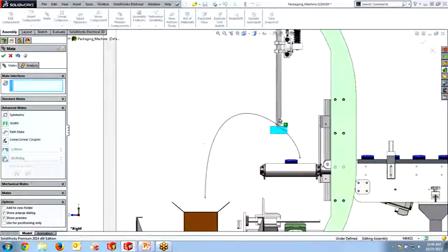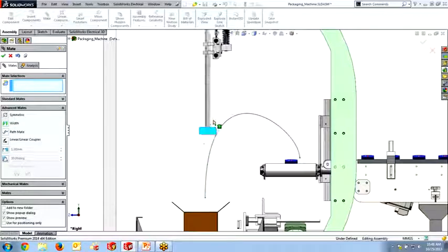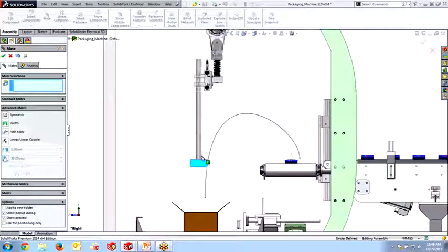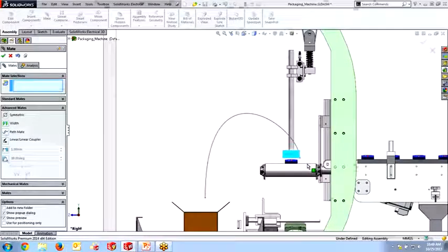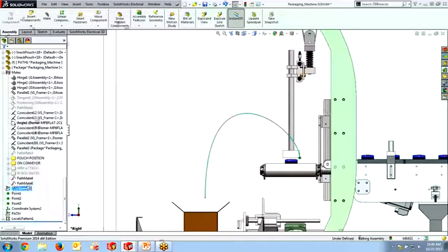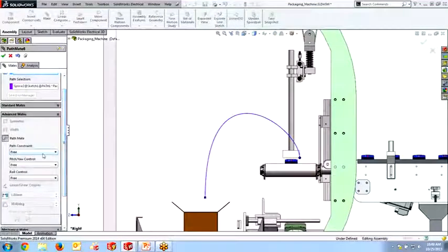Okay, so you can really control specifically the path that you want your more free-form and free-to-move components in the assembly. Control how those are meant to actually move in three-dimensional space. Constrain them in some way while still allowing for some pretty free-form movement inside of that range. Okay, so path mates are exceptionally useful for this, and they can be controlled in much the same way as that slot mate. Okay, so they have some similar controls here.